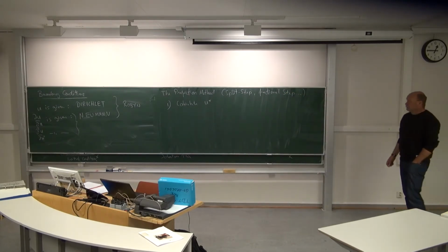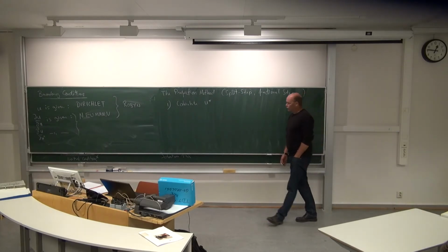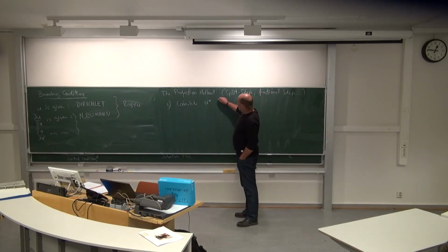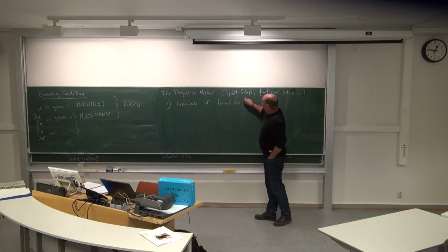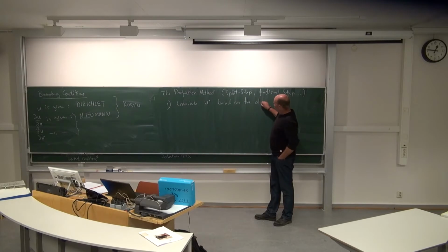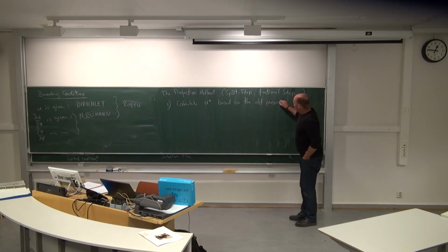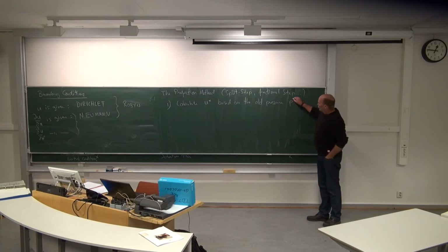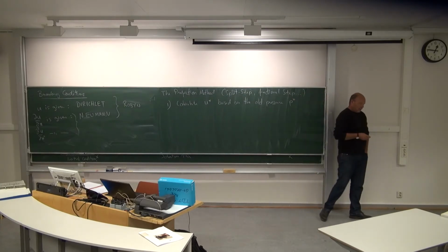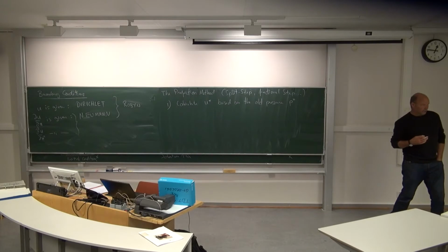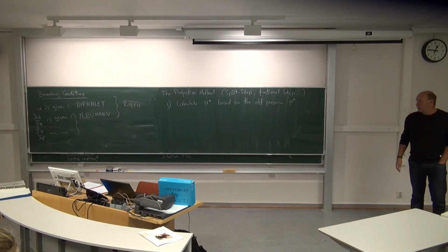It's tentative, meaning it's wrong in general, because it's based on the old pressure, meaning the pressure from the previous time step, not the pressure from the new time step as it should have been, but that's one equation with 2 unknowns, so we can't do it.